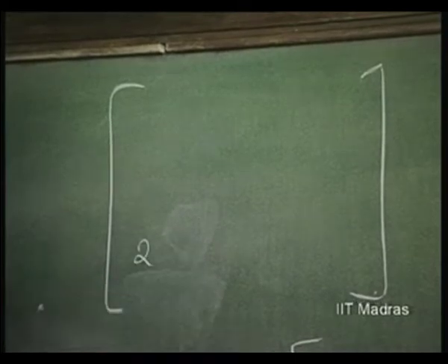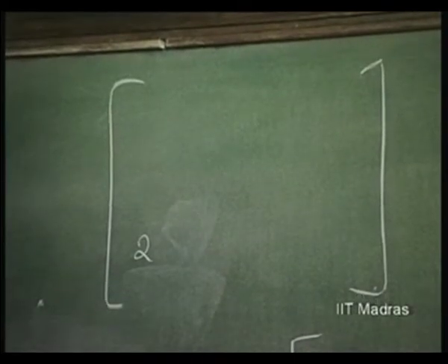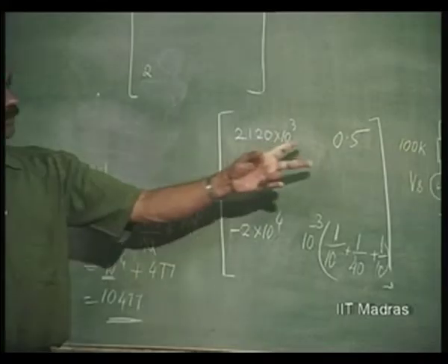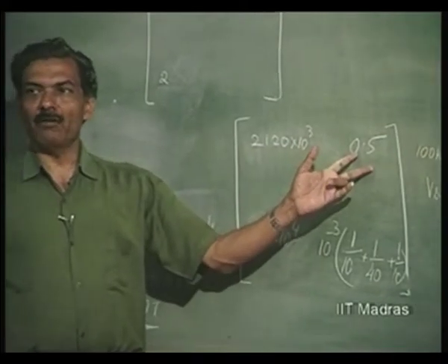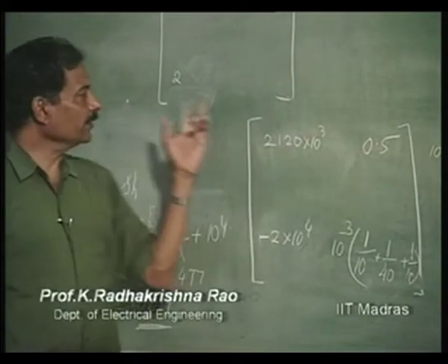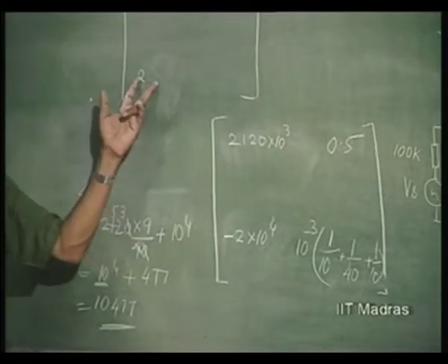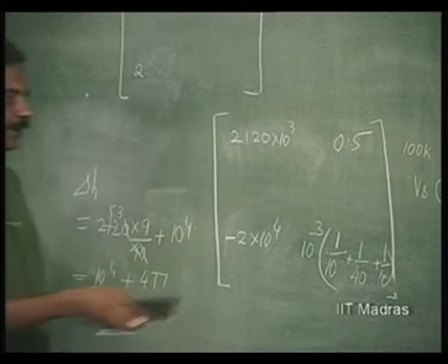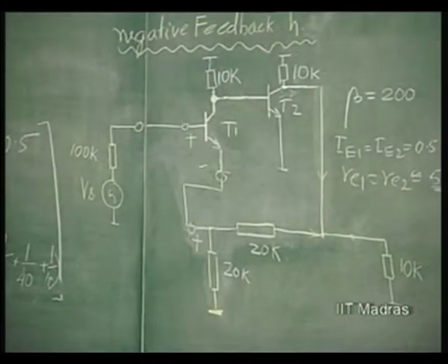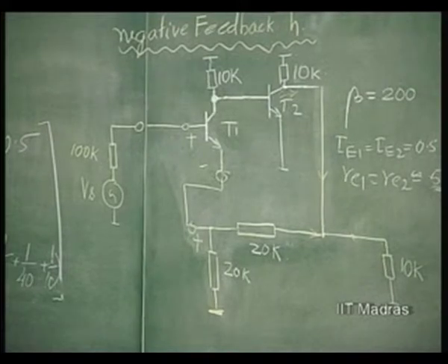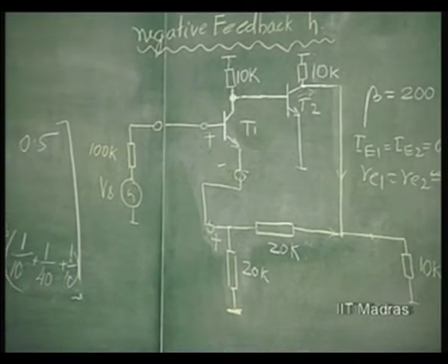You can see that is what has happened. We had a feedback factor of 0.5, 1 over 0.5 is what is going to appear as GF, 2. That is purely determined by these two passive resistances 20 k and 20 k. Nice.